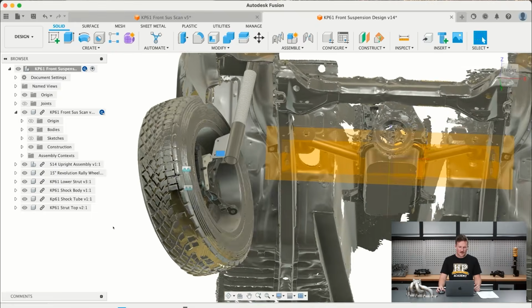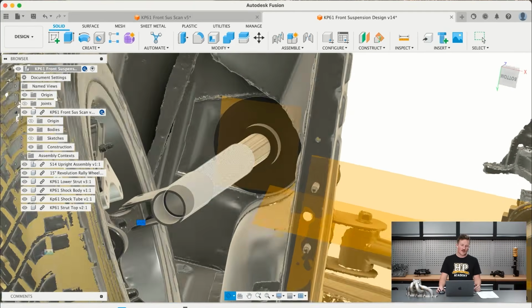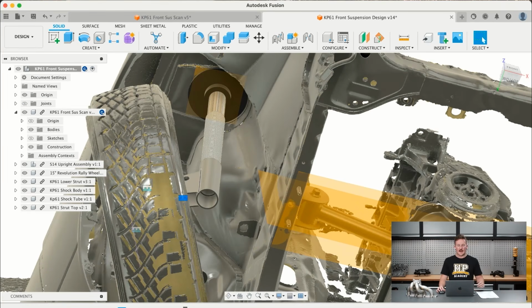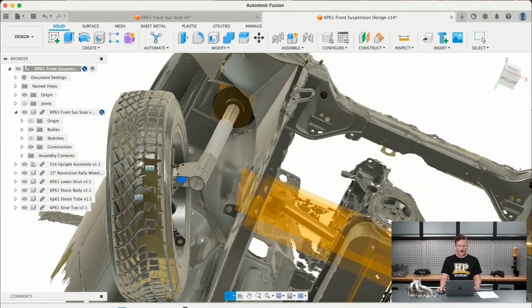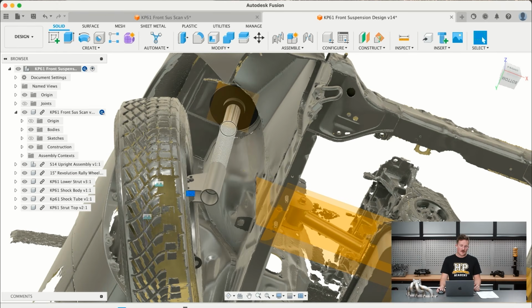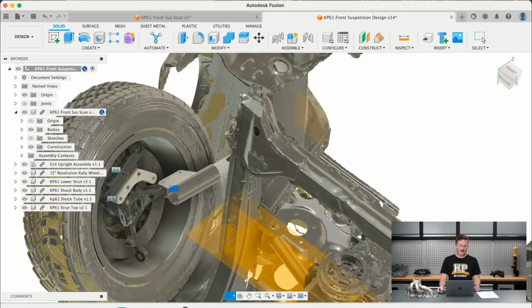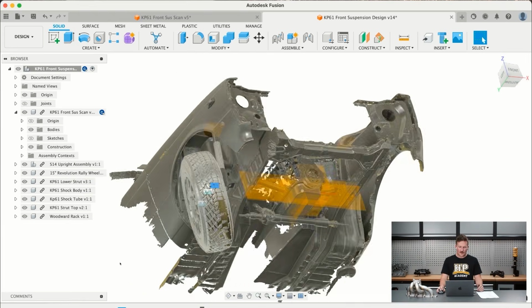About here is a very basic model of a coilover that he's looking to possibly purchase for the car. It's a gravel rally coilover that will fit to the S14 upright. I've set it up with a ball joint at the top here, a bit of a slider here to simulate the damper movement, and then this is fixed down here rigidly to the upright, as it would be in a real situation. So we keep progressing through.